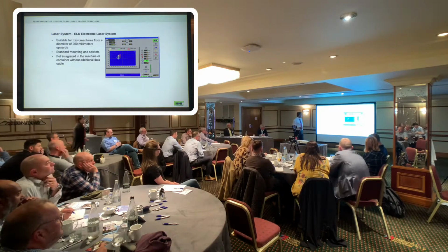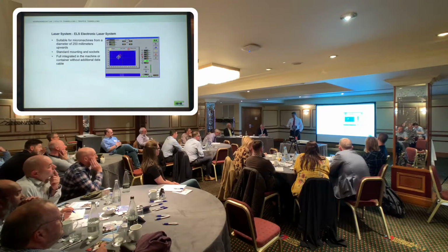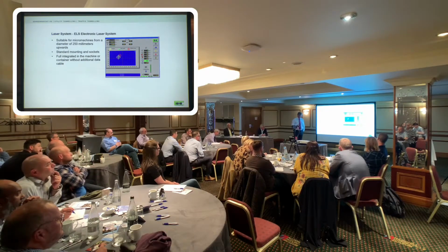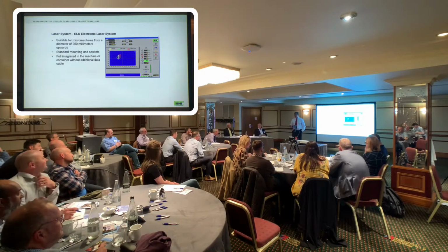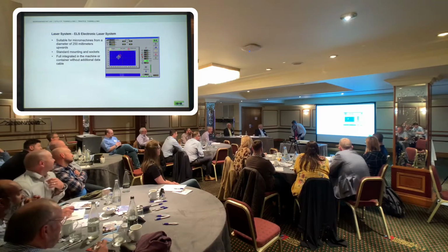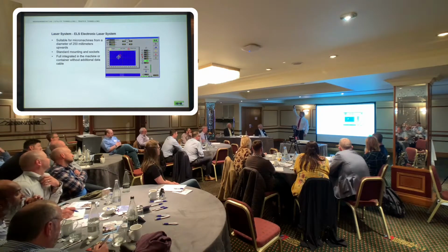That's the ELS laser guided system. Somewhere in the shaft bottom is a laser. It's been set up by an engineer, it's been checked. Somebody's made sure that the grade you've dialed in is the right way round. So the gang aren't sitting there, and it comes out up here.